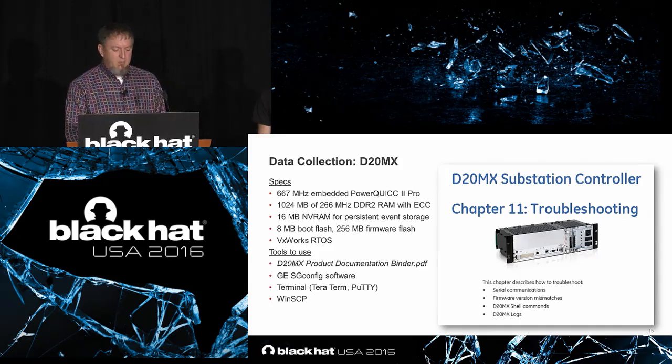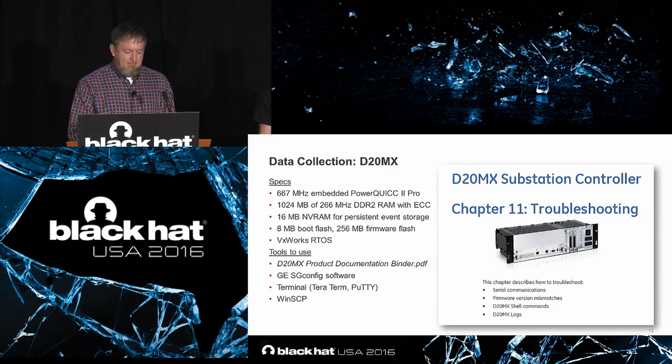PowerQUICC II Pro processor on this D20. It's got a gig of RAM. It's got VxWorks. If any of you are familiar with the substation world, you're probably familiar with this device, and you probably have these manuals already. So this is for you, some information that you can use in case you need to do some forensics, even if it's troubleshooting an actual configuration problem.